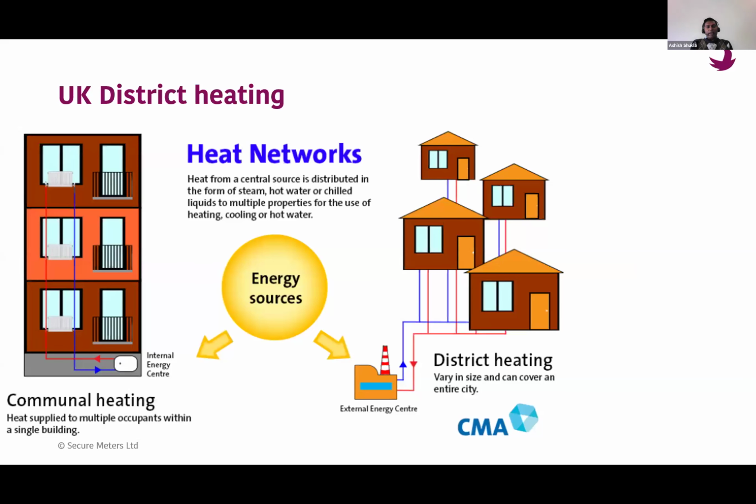So now I'm switching to another topic. You have seen the power system, digital substation, smart grid perspective. This is also very interesting. I just wanted to give you a different flavor which you will not be seeing in your day-to-day scenario. This is about the UK district heating use case. What happens in the UK or any other cold countries where there is no dedicated district heating concept? Now you will ask, what is district heating? District heating means you boil the water centrally in one place, and then from there you distribute this hot water for domestic hot water consumption or for space heating purposes.